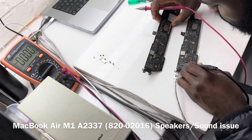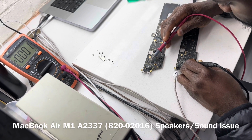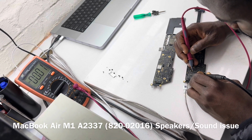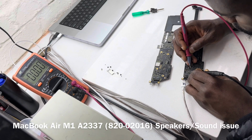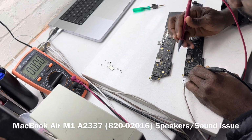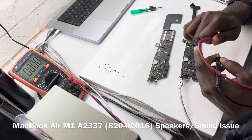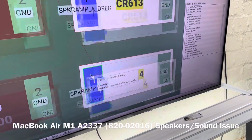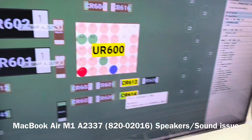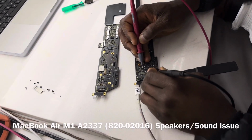Oh, I see that. Okay, there's a slight difference here in design. Let's see this. 1.2. So here we're getting 1.2, but in the case of the other one we actually got 0. We measure 1.2 for speaker underscore AD reg, but on the board that is not working, we are getting 0.